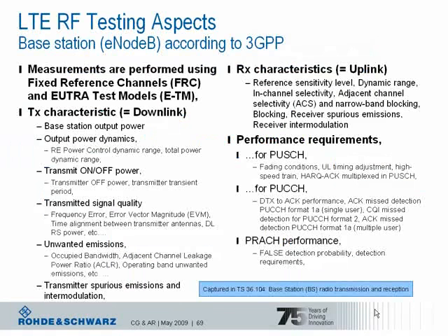Conformance testing of an LTE-capable base station is captured in 3GPP technical specification 36.141, based on technical specification 36.104, where base station radio transmission and reception is described. Transmitter and receiver tests are defined as well as performance tests. These tests are performed using well-defined fixed reference channels (FRC) and so-called UTRA test models.